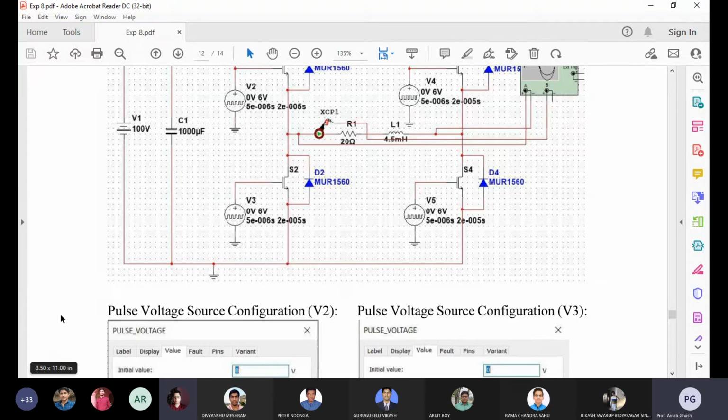Then in the second and fourth quadrants, one of the components, voltage or current, will be negative, so power is negative. So it's the 4 quadrant operation of the chopper. You know the 4 quadrant operation of DC drives, so we also use the full bridge configuration as a chopper for the 4 quadrant operation of DC drives.